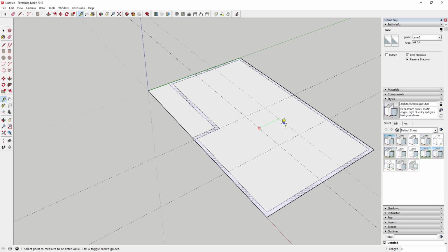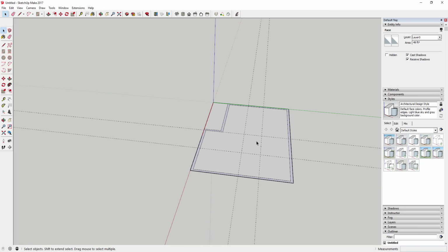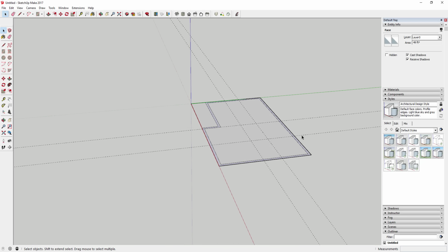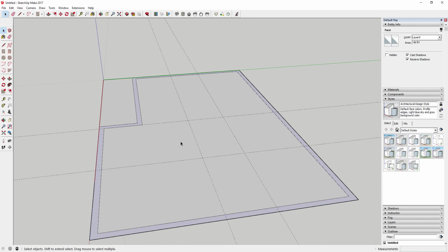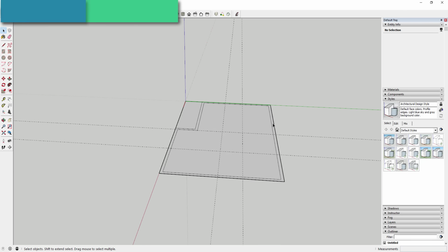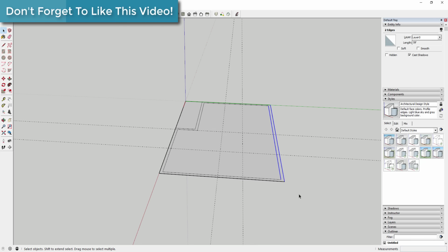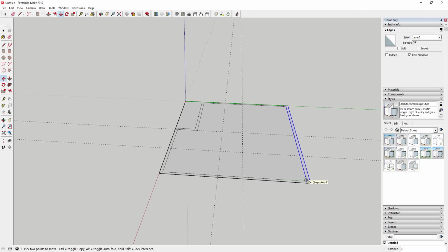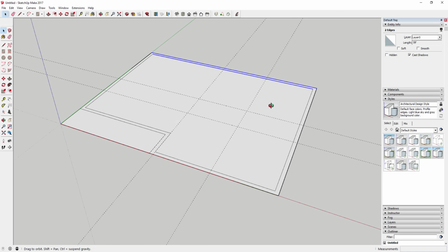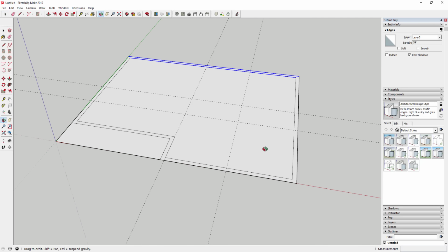And then let's say I wanted a little hallway in here, and you can see how again this is a little small. So if I want a 4-foot hallway in here and I want these rooms to be 9 foot, that means this house is going to have to be a little wider. So what I can do is select these lines, and I can just move this out along the green axis another 4 or 5 feet. So let's say I move this out another 4 feet. So I'm basically just roughing out my shapes.